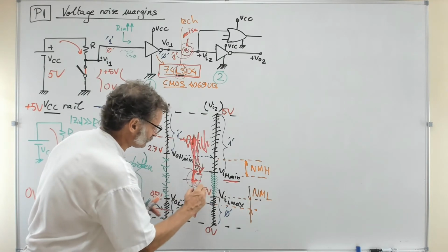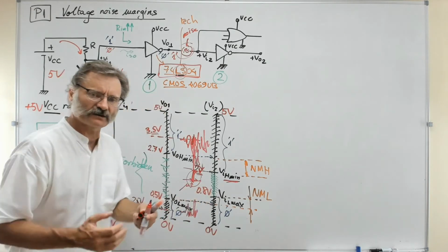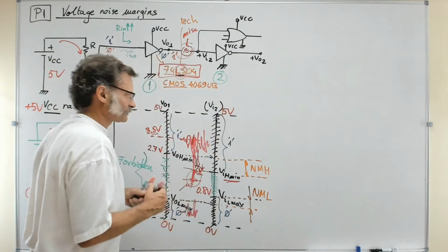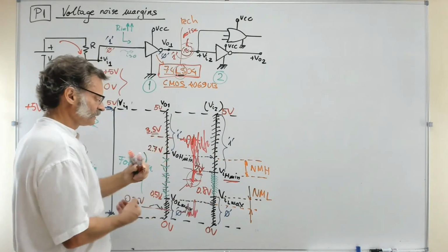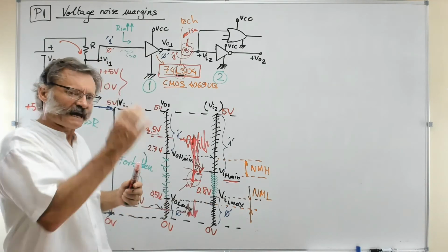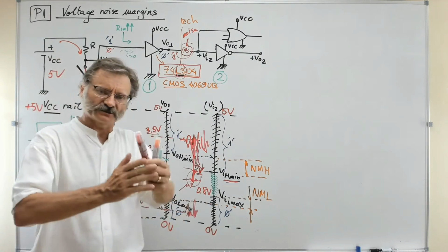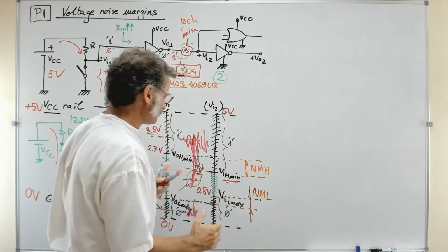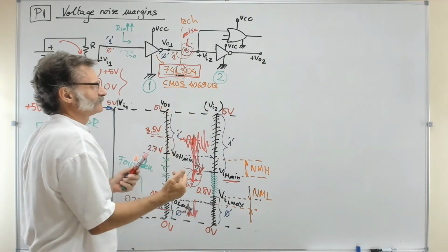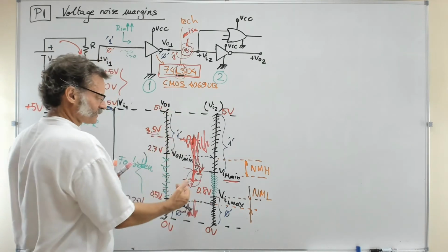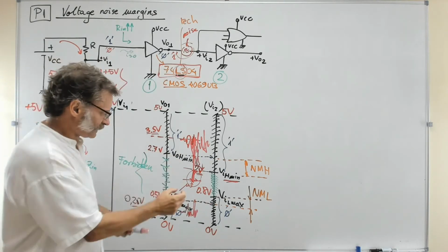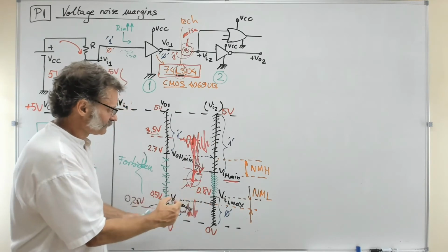Perhaps this is only a few microseconds, but you know, a microsecond for a digital circuit is a huge amount of time. It works in the range of nanoseconds, and we will see. So a microsecond, even if it's that short, a spike that short, doesn't matter. It is a huge amount of time for a digital circuit of today's technologies. Perhaps not like that, but the FPGA technologies of today work with very, very tiny in-time signals. So that is a very long time, 1,000 nanoseconds.